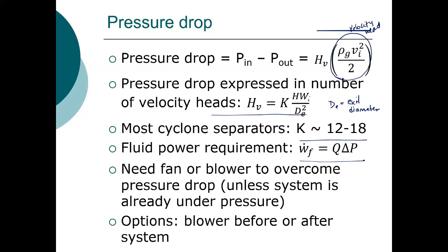If we put it before, do we have any problems? What would be a problem of putting the blower before the cyclone separator? Okay, so we've got a cyclone separator. We can put the blower before, or we can put it after. What's an issue with putting it before? Gas is dirty, so if we put it before, then it's likely that that particulate matter in the gas can get into the bearings, can collect on the blades. That's going to throw the blower out of balance. You're going to have excessive vibration.